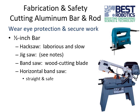A hacksaw is actually, I think, a really good way to do it. Sure, it's a little bit slow. You've got to put in some muscle power for it, but it's safe, it's pretty well controlled, and you don't need a lot of special equipment for it. I've done it this way before. I've cut it with the hacksaw, and it'll work. Just make sure you have a good blade for it, and they make metal cutting blades for hacksaws.